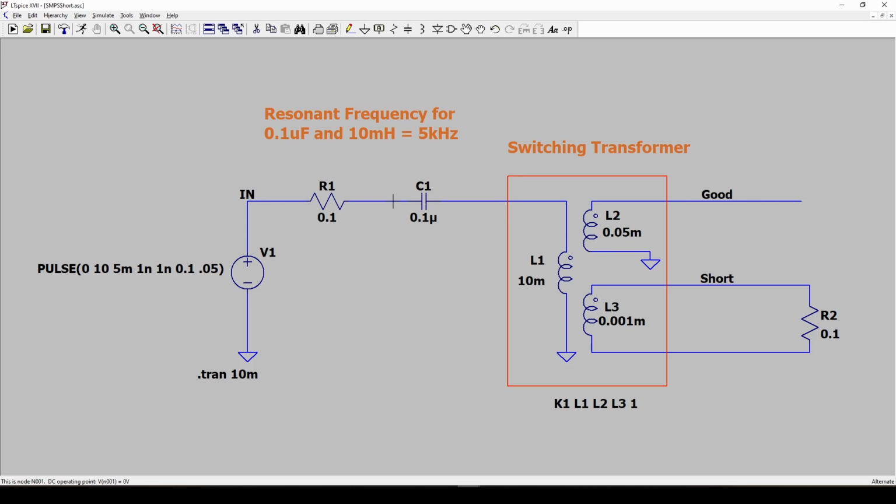So if you look at this circuit, we have chosen some values of inductance of the transformer winding, capacitance for the resonance circuit, and resistance that simulates the resistance of the inductance winding. Also, you've got what's called ESR of the capacitor, equivalent series resistance. So you've got a resistor inside this capacitor. You've got wire resistance that you're simulating. You've also got a voltage here that we've selected, 10 volts.